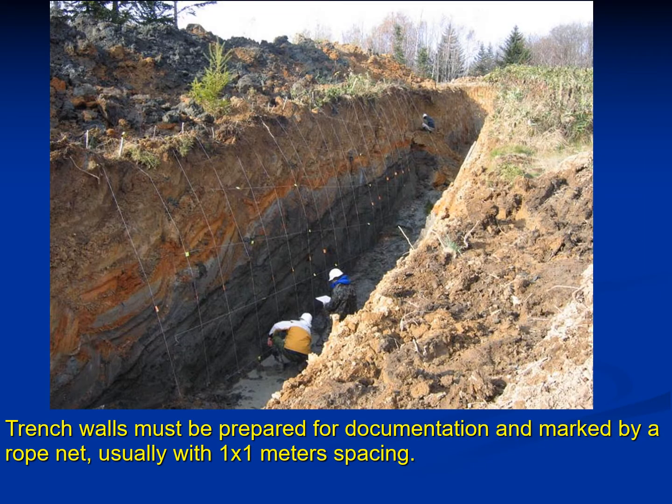One more trench in Sakhalin, it demonstrates the necessity of very accurate preparation for documentation. Trench wall selected for documentation must be cleaned and marked by a rope net, usually with 1 to 1 meter spacing.